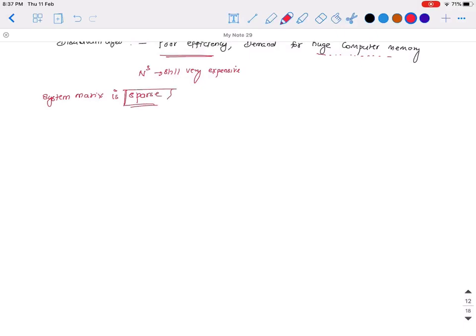Do you remember what we mean by a sparse matrix? That they contain a major number of zero entries. If you take the matrix that we obtained from our example, the one-dimensional heat conduction problem, it has non-zero elements only along 3 diagonals, and all other entries are 0.